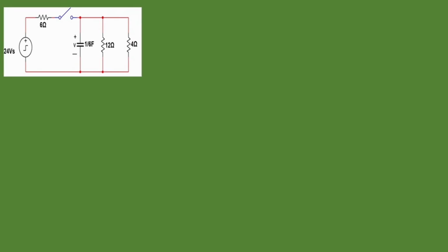Alright, so it's best practice when you're solving RL and RC circuits, your solution is usually going to be divided into 2 parts. Solving for t less than 0 and solving for when t greater than 0. And each of these have different objectives. When you're solving for t less than 0, you're looking primarily for your initial conditions. So what does that mean? You're looking for V naughts if you're dealing with RC, and you're looking for I naughts if you're dealing with RL circuits.